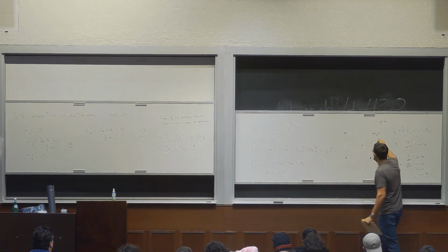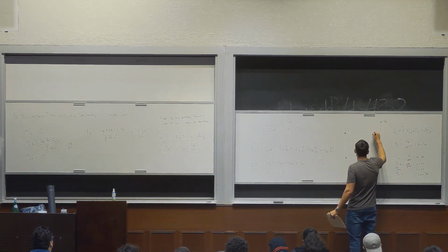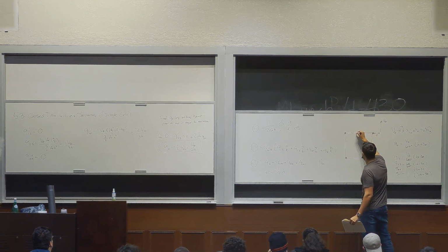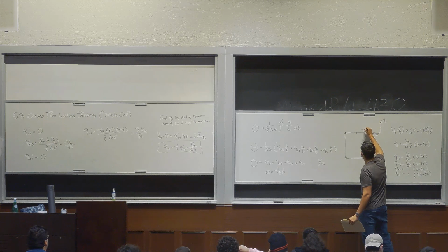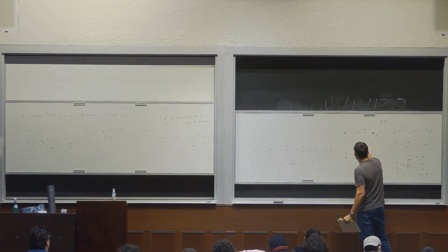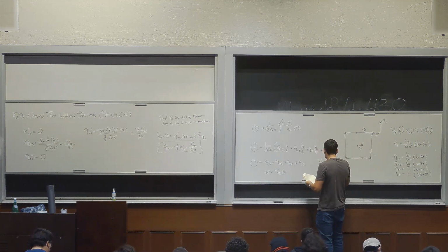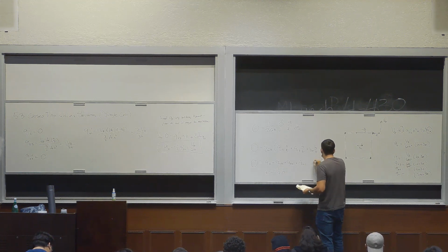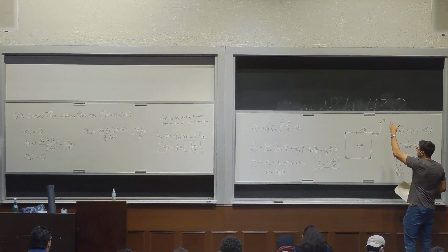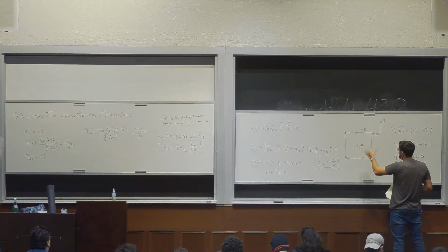Now we know E is -1/2 H from the original location. So this right here is YSC, which in this case equals -H over 6. If VZ was acting at the location -H over 6, then this thing wouldn't twist.